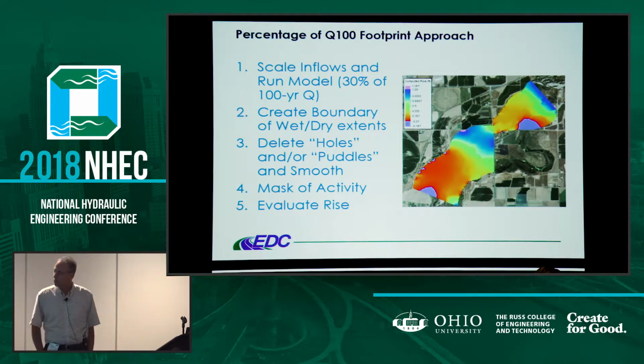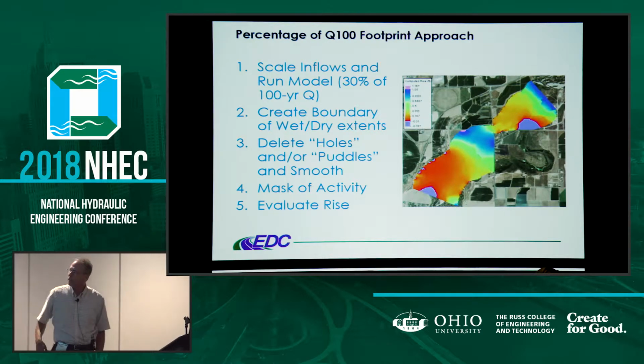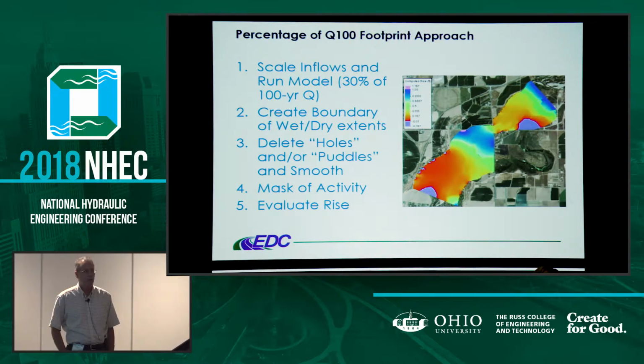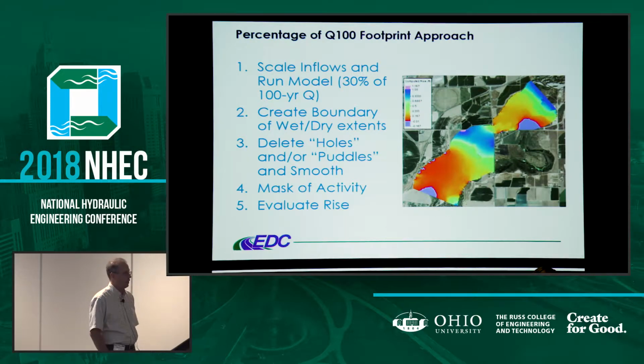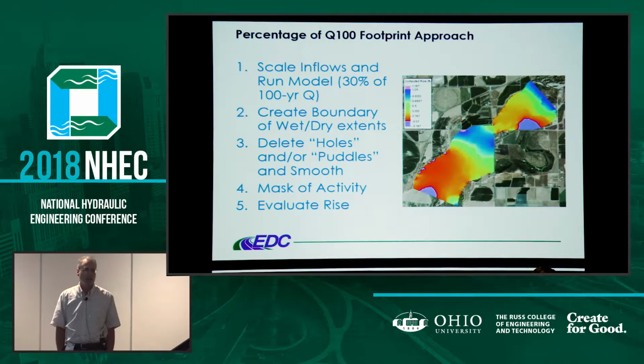Now this actually created a different observation for us. The purple areas on the upper right side and down at the inflow boundary are actually decreases in water surface elevation. The 1D assumption says that any decrease in the water surface elevation must be drawing us towards critical depth, and that's bad, so that can't happen. It's not allowable in a floodway.